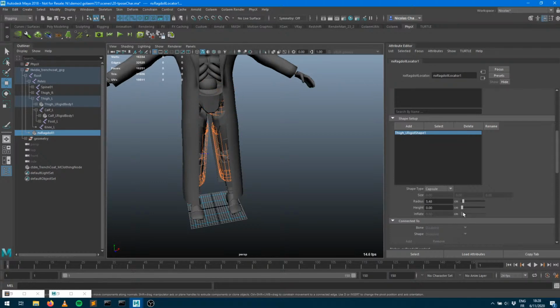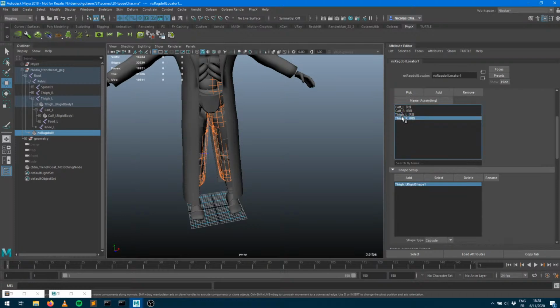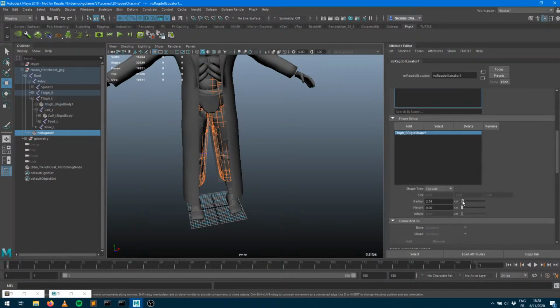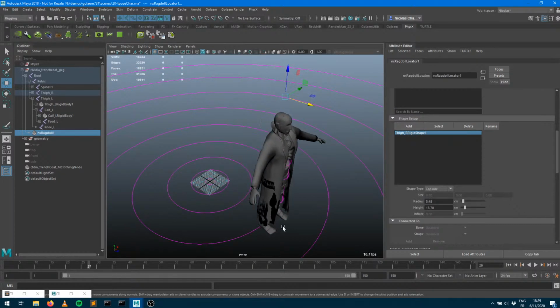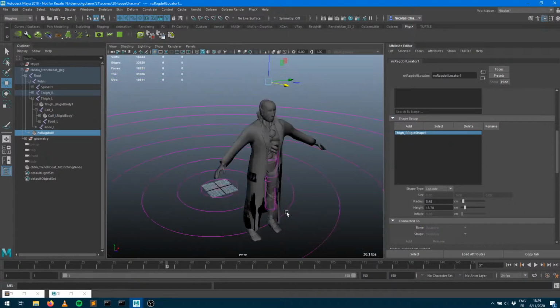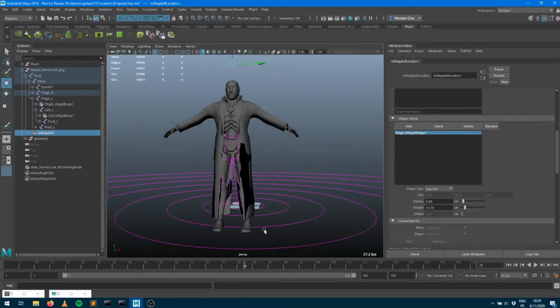You're kind of making your character here in terms of rigid body, and that will act as a collider for the physics system, which means that now if you do your physics, your cloth simulation with all that deformation that I just applied, now you don't have that collision anymore. So probably there are some vertices that I haven't painted correctly, but more or less it's the idea here.